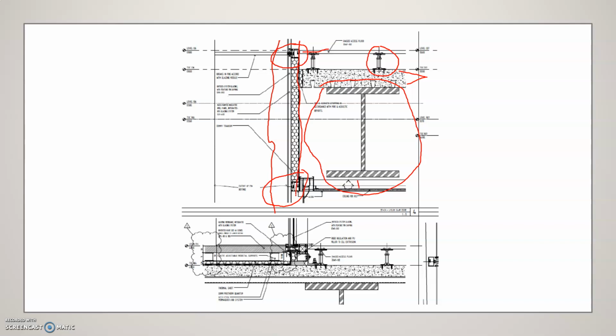We go mullion, and then we go transom here. One transom here, one transom there, and another transom here. We'll have to put some sort of bracket fixing back to this floor slab, and then we put a restraint bracket on this floor slab as well.